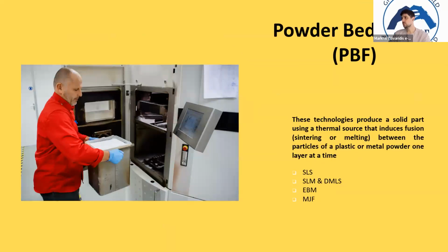The third one and the last one that I would like to discuss to show you is the powder bed fusion method, which uses either a laser or an electron beam to melt and fuse material powder together. Now, all powder bed fusion processes involve the spreading of the powder material over previous layers, and a hopper or a reservoir below or aside the bed provides fresh material supply.